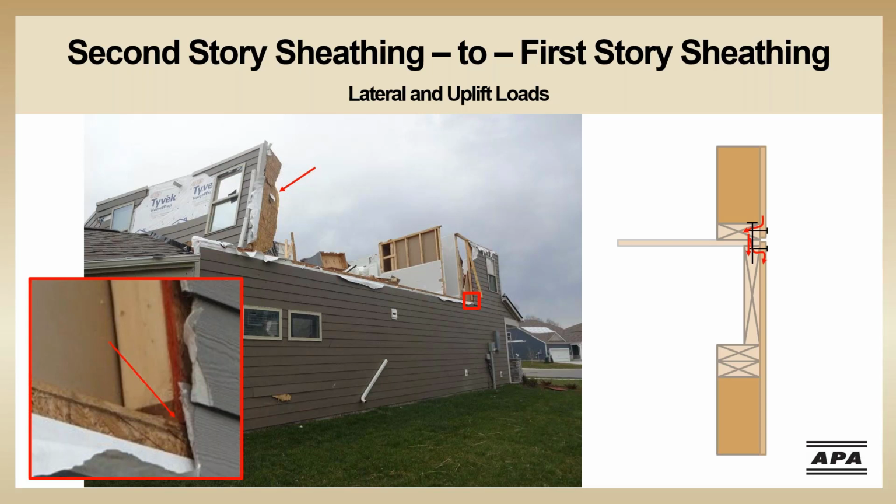The complete loss of the roof of the home likely also contributed to the failure of the walls. Without the roof system to support the top of the studs at the upper level, the load path was incomplete and the wall system was weakened because of it.